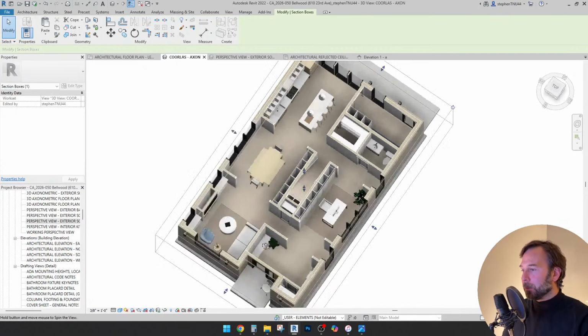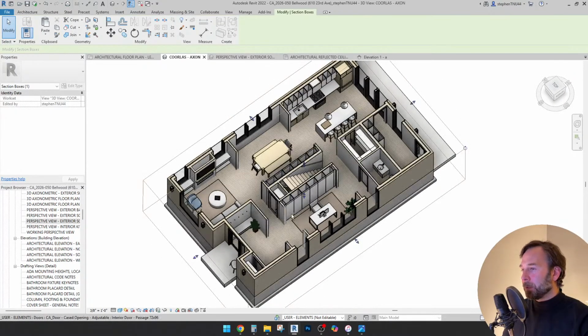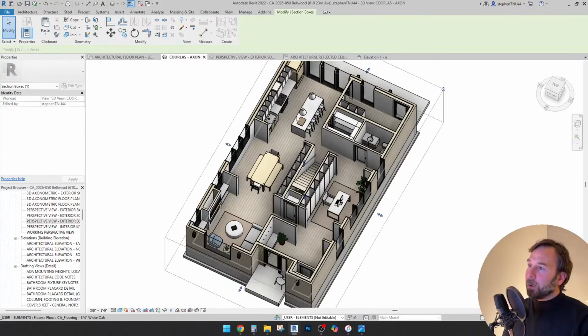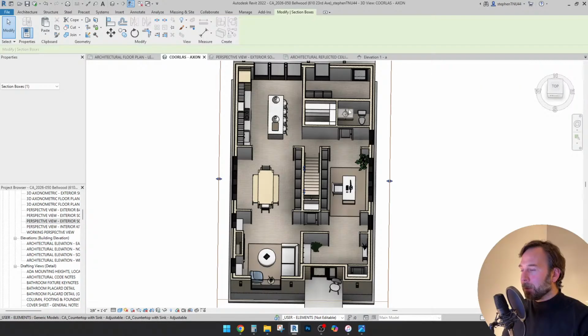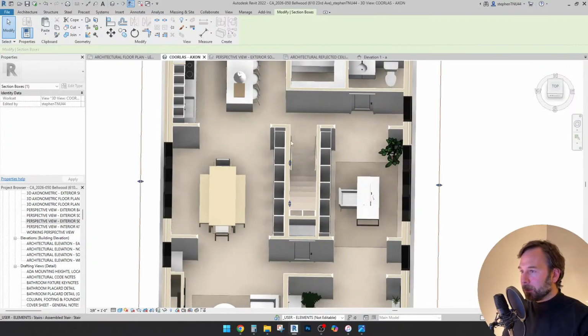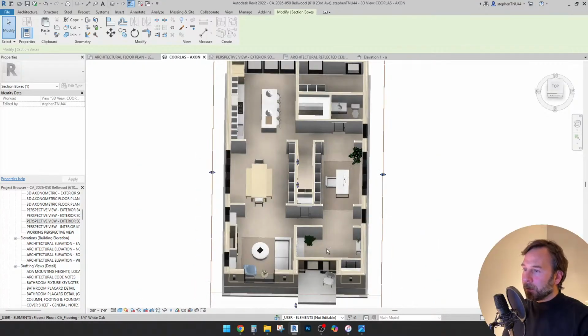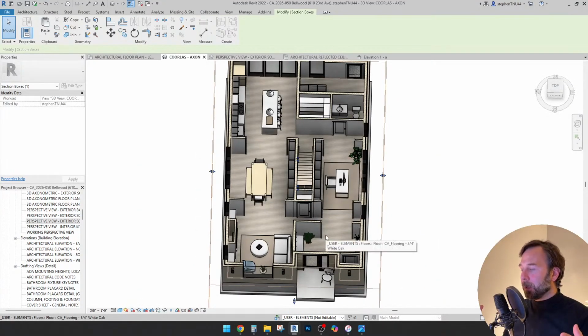We've got the informal living space here, and then the kitchen will always remain in that kind of sector there. We've grouped the utilities and some of the storage area back there. Same thing with the storage and the stair here. So we tried to group and compartmentalize these spaces and leave some flexibility for adaptability of the floor plan for different use cases.